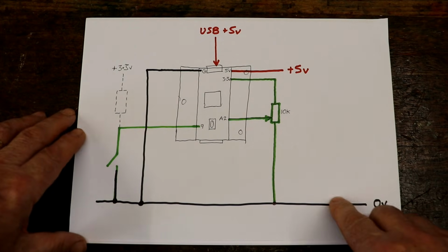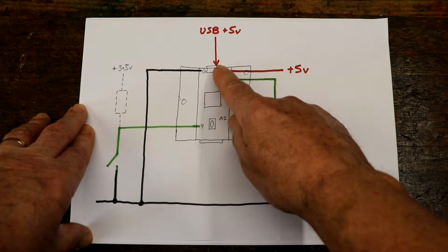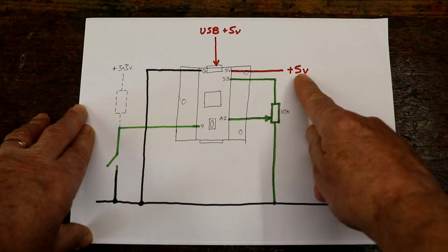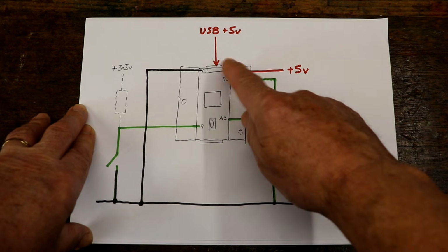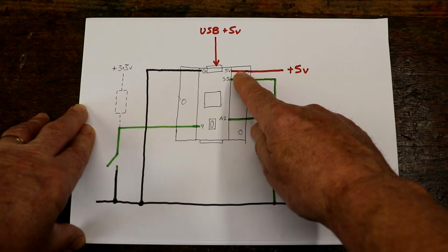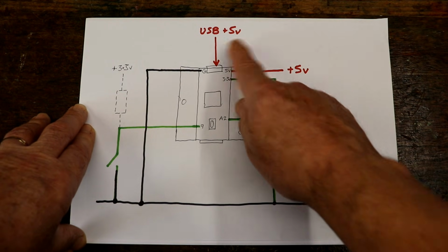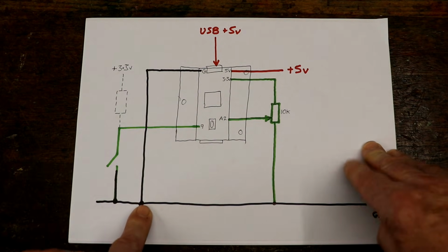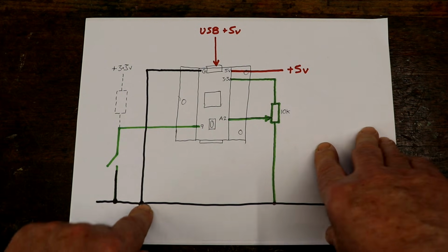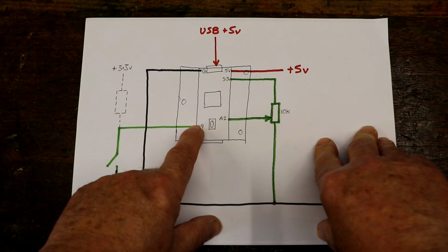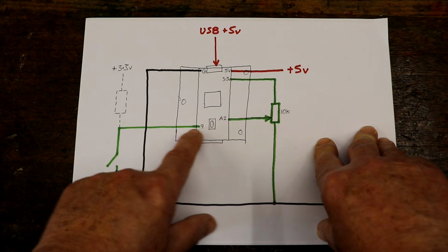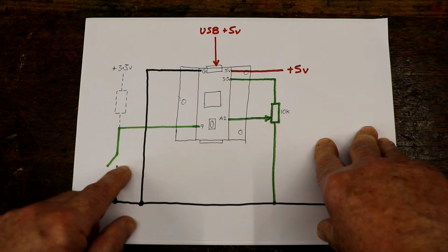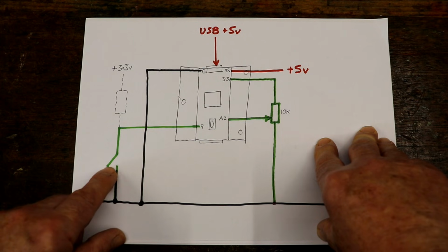So to reiterate, you can run the Teensy from either USB 5 volts plug-in lead or from a plus 5 volts connected to the 5 volt in, but not both, not at the same time. I've checked and they clearly state you mustn't use them both at the same time. You connect the ground to the common ground or 0 volts. If you want to have a switch connected to one of the inputs, set as an input, you connect the input to the switch and then the other side of the switch to ground. So the switch is actually switching to ground, on and off, so to speak.